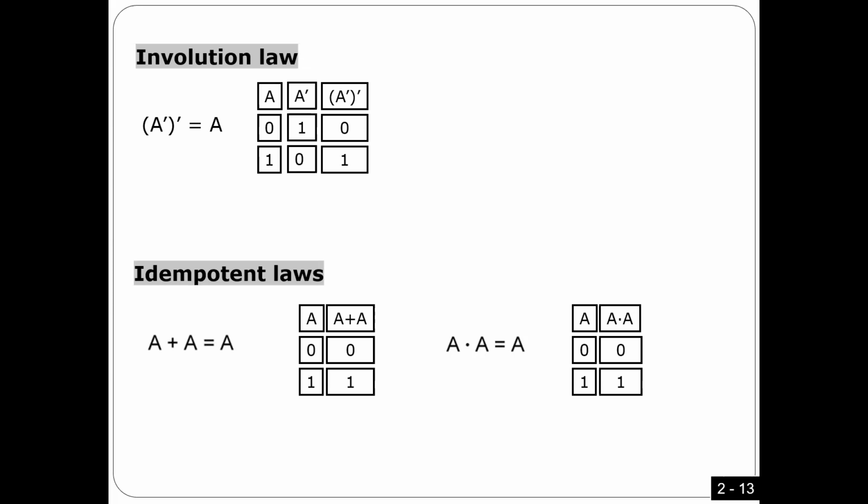Now I have also here what I'm saying here. One of the rules we have here is, if you have A OR A, I'm going to get A. What is the logic? I'm going to tell you what is the logic. The two values are the same, A and A, right? So this one has only two cases, 0, 0 or 1, 1, right? So in case 0, 0, I'm going to get 0, right? 1, 1, I'm going to get 1. So it's the same.